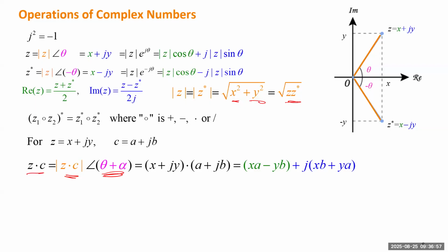So when you do multiplication, this formula is the easiest way, because later we'll do calculations for power. If you have voltage and current, you always need to do multiplication. So usually change voltage and current to the phasor representation with absolute value and angle. So this is easier. If you really want to know the real and imaginary parts, you can use this formula. That can be easily proved. But usually I don't remember this one.